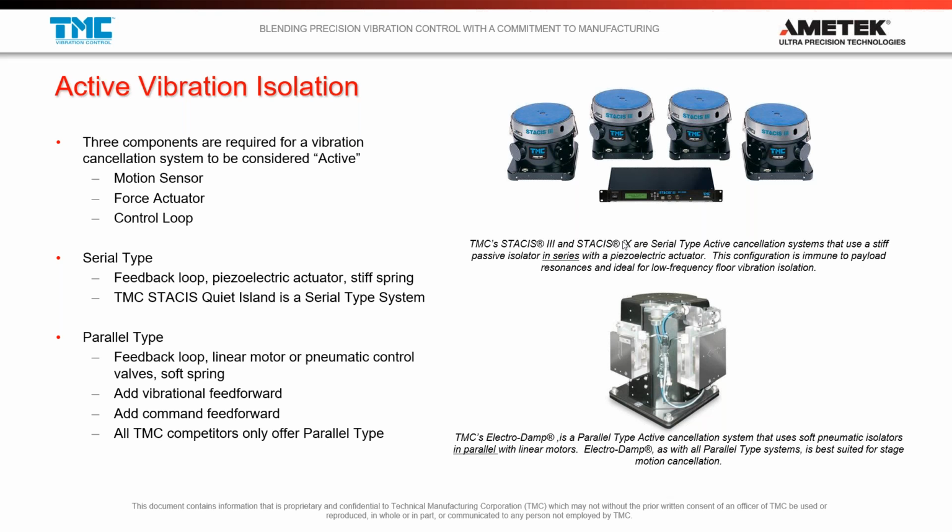And so passive isolators are a good way to support optical tables. And if you have no sensitivity at these low frequencies where these isolators are going to be resonating, then you're probably okay. So we see a lot of optical tables out there supported by passive systems with resonant frequencies.